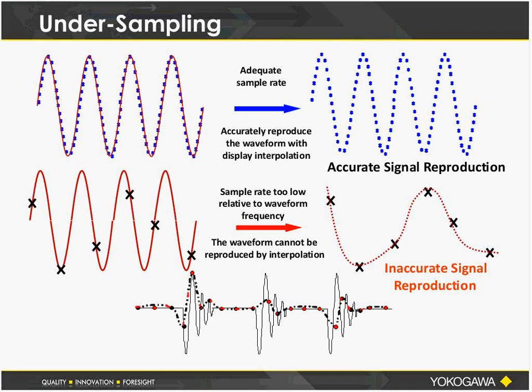So it is important to keep an eye on the sample rate of the instrument, not only the sample rate spec of the instrument, but the actual sample rate that is being used at all times in the instrument.